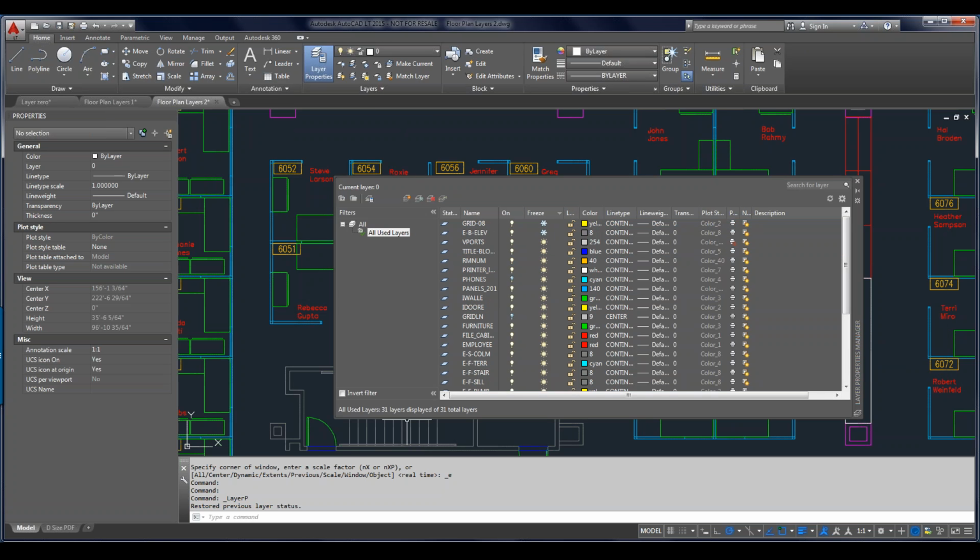Only 31 are being used, okay? But you can get 400, 500, 600 layers, and 100 of those are turned off maybe. And you're just doing something in the drawing that you maybe really are viewing to see how far the project is or whatever, and you have to turn on those layers or thaw them. But then you have to put them back by the time you're done, right? In case if you make an annotation, you can't just close without saving.